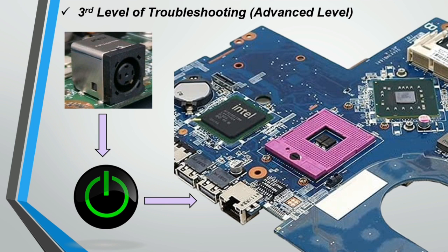So if you check the power button and you find it okay, then the problem is not in the power button, and it is not in the power jack. The problem is in the motherboard itself.